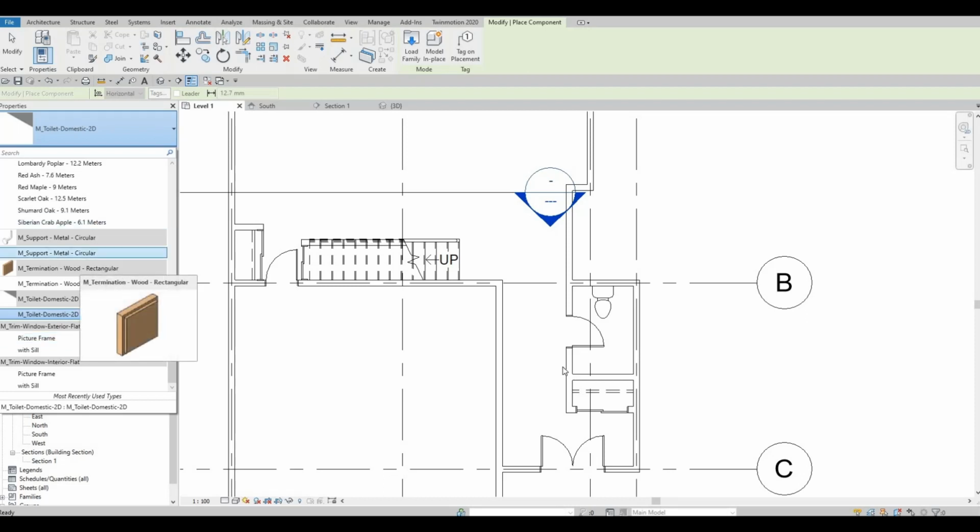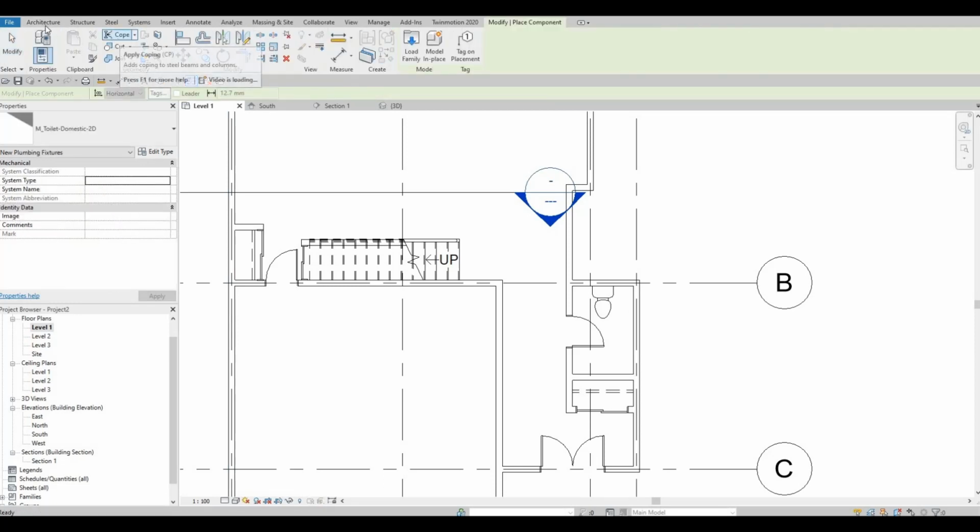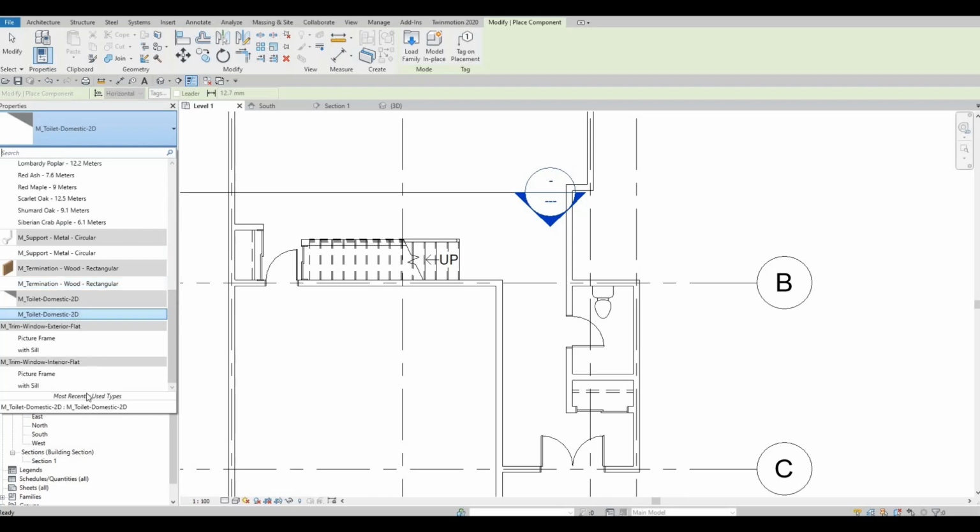But by using CM, the process that I want you to do, and I think this will make everything fast, is once you insert something, add it already on your drawing. And then by using CM, you don't need to click the component here or go to architecture, click component, and then look for it.